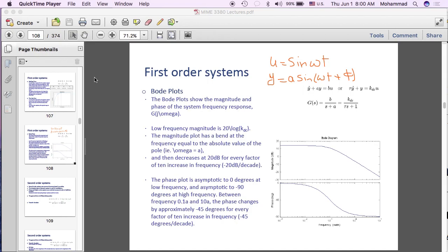And let me remind you that response of dynamic systems have two parts: the transient portion, which would pass over time, and the steady state, which is what the response will converge to over time eventually. So the message there was that by having the model, you can get insight to both transient response, which is the speed of the response, as well as the steady state response, which is the value of the response, KDC. If you recall, we looked at a MATLAB tool to get us the response.